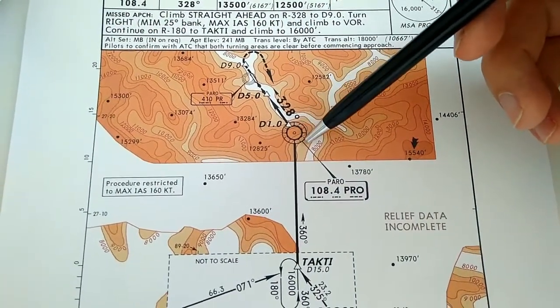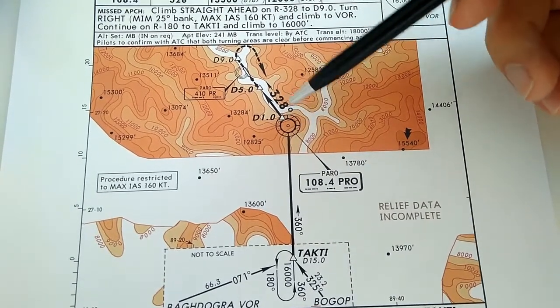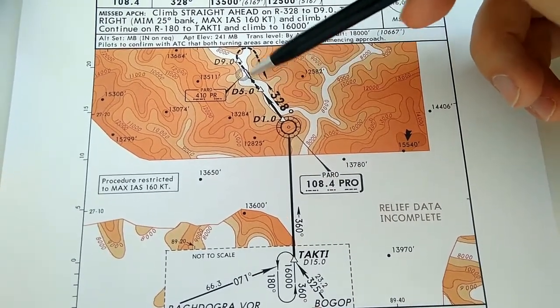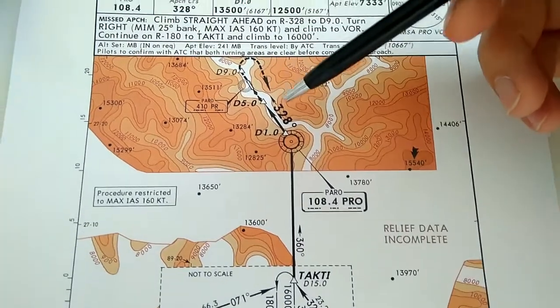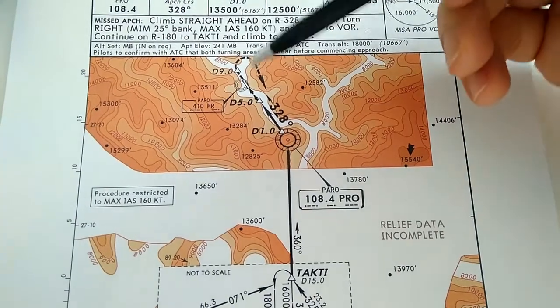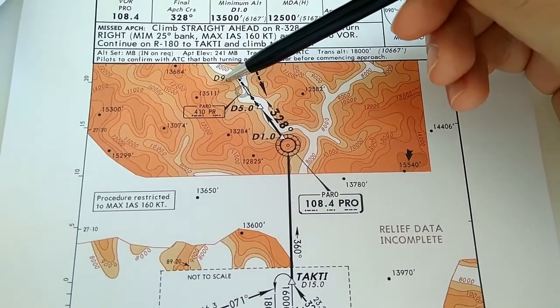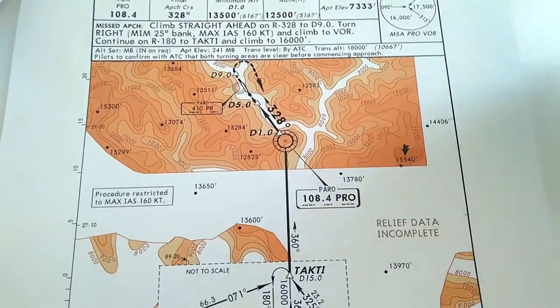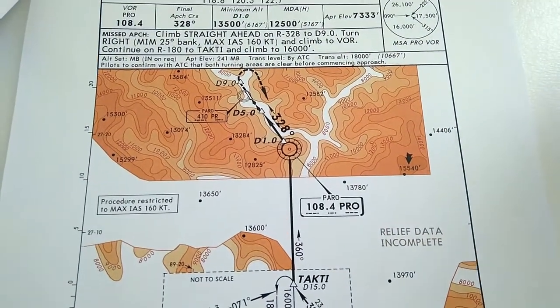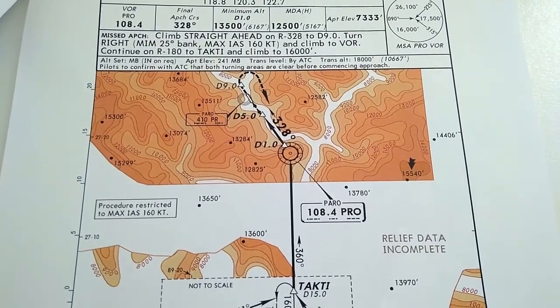That means we'll leave the runway on the VOR on a heading of 328 until we pass the airfield. It's very crucial to have the airfield in sight, because otherwise you cannot execute the approach. And then, as just shown before, we make the left turn and the right turn back to our airport. Let's see how this looks like in the simulator.